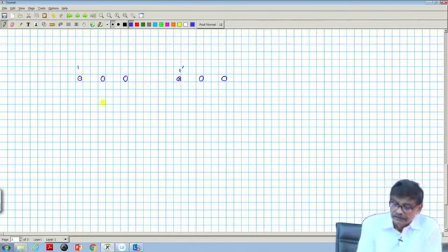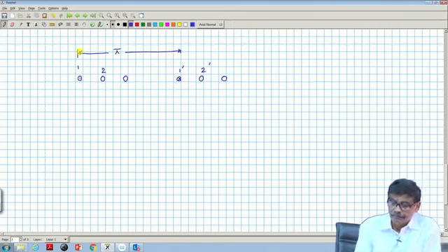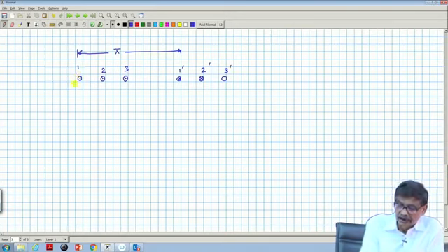This is coil 2, its return is here 2 dashed and these angles are pi, mind you, full pitch coil. This is pi electrical or 180 degree electrical. So, 2 dashed. In our case, they will carry the same current, similarly 3 dashed. Got the point?